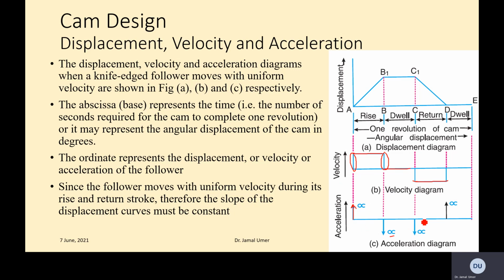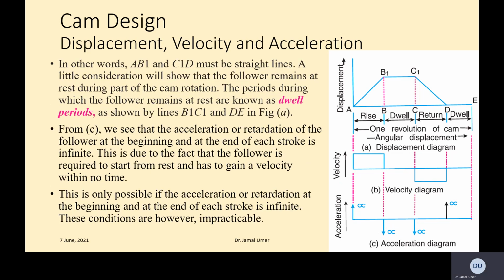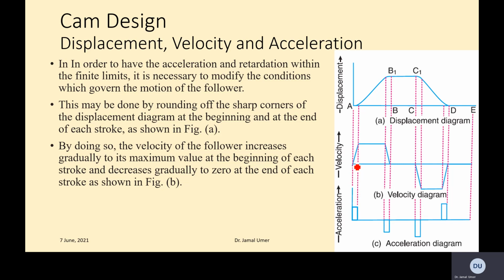So this is not really the case in actual cams. So then this modified one was discussed. You definitely need some time to arrive from zero to maximum velocity. Even if it's quicker, you still need some time. So when you need some time, what does it mean? It means it has some definite magnitude of acceleration. This is what it actually means. So now you see that instead of infinite acceleration, you get finite acceleration, or deceleration when you have the return.